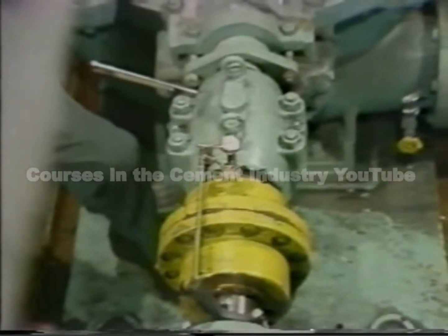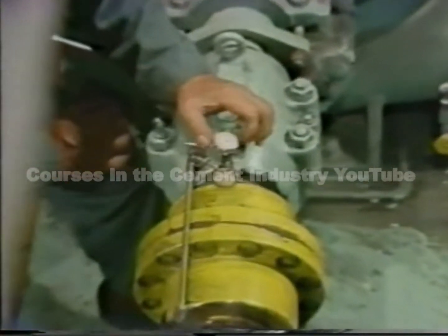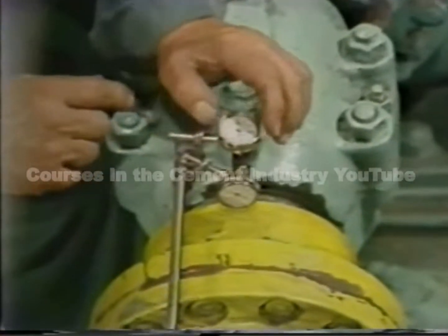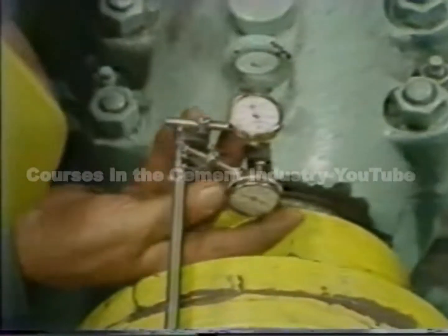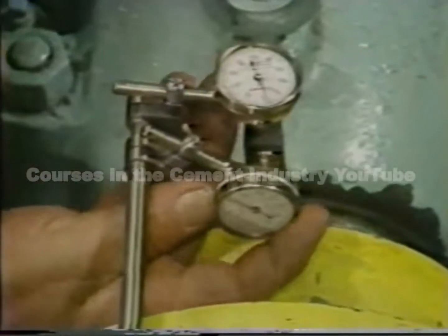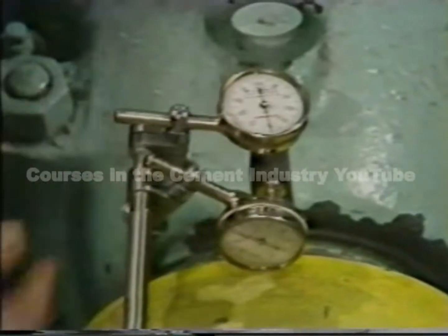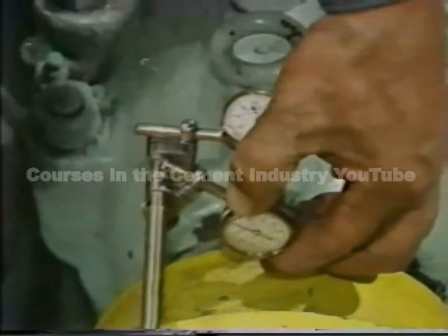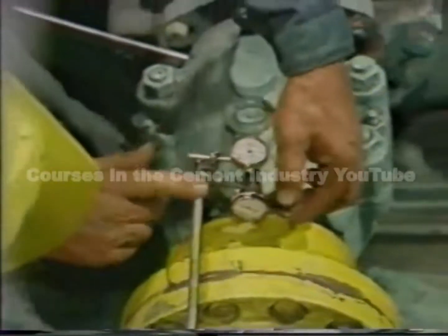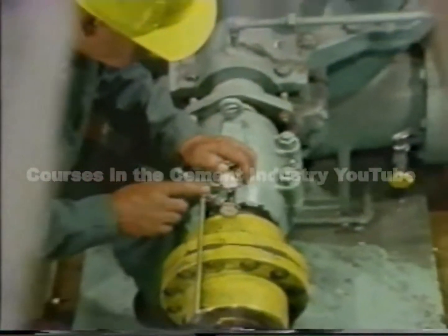With these marks made, the technician zeroes the dial indicator for the parallel reading, and then zeroes the dial indicator for the angular reading. Touching one dial may cause the other dial needle to move, so be sure to double check that the dials are still at 0 when the adjustments are done. Once he has both dials set at 0, he can move on to the next step, which is to rotate the shaft one complete turn.